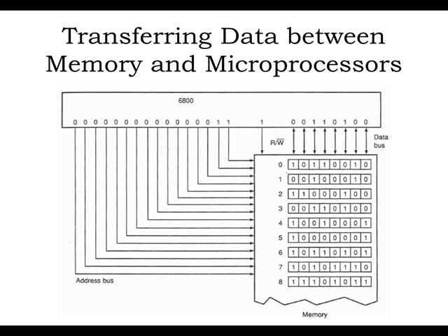Now, to do this one loading, what do you have to do exactly? A couple of things. First, you have to enable the reading line. Before that, you have to determine the address, because you will be choosing only one location out of millions of locations. That address will be here. And then next, you choose either read mode or writing mode. Now you choose read mode, then that byte will be here, and the microprocessor is reading because that byte is read.